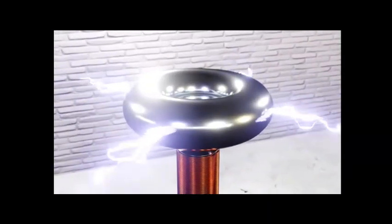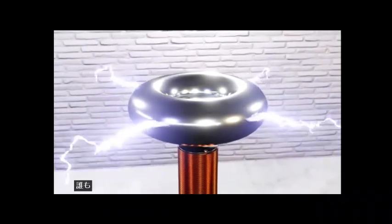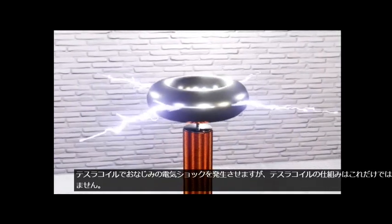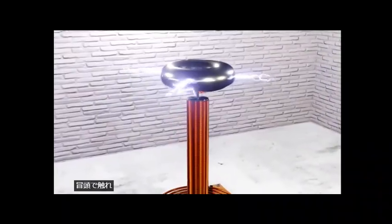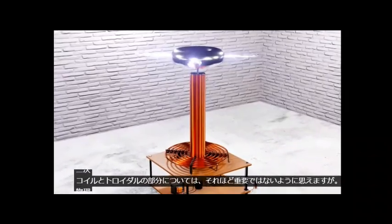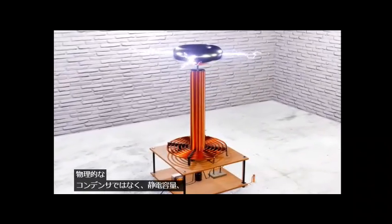Because we had more accumulated charges ready to jump, generating the electric shocks everyone knows and loves from Tesla coils. But that's not all about how a Tesla coil works. Do you remember the properties of resonant circuits that I mentioned at the beginning? Although it doesn't seem like it, the section with the secondary coil and toroid form a new resonant circuit in which there is not a physical capacitor but a capacitance.